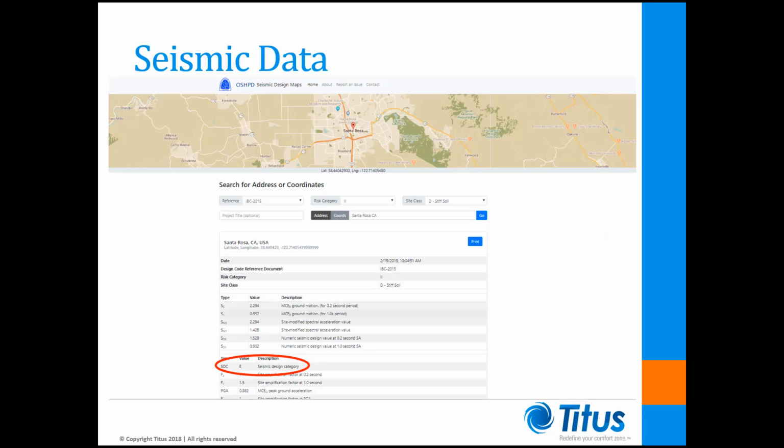With these two key pieces of data along with the site's location, a full seismic workup can be generated online. As of this recording, the USGS has discontinued their own graphical user interface online app. There are, however, a number of other third parties that have created their own apps based on public data provided by the USGS. Links to these outside entities can be found on the USGS Earthquake Hazards Program website.